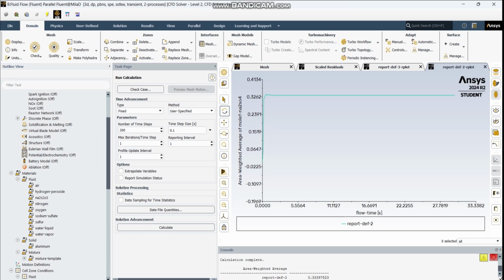Actually, this enhanced turbulence reduces the concentration gradients and ensures that the reactants are brought into contact more frequently and uniformly throughout the reactor. As a result, mass transfer resistance decreases, which is especially important in reactions where the mixing rate is comparable to or slower than the chemical reaction rate.